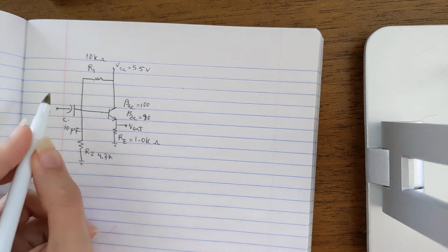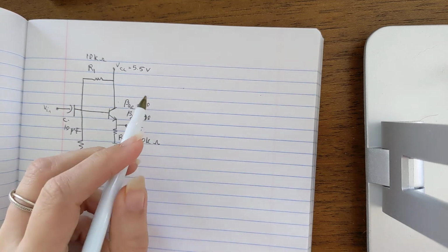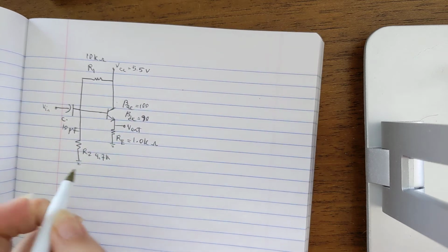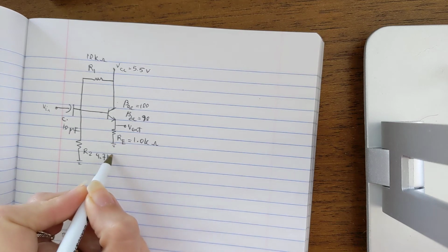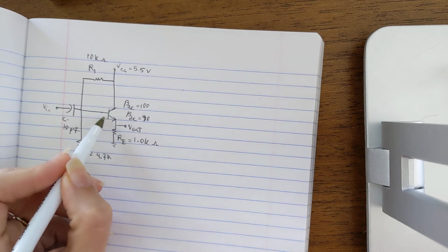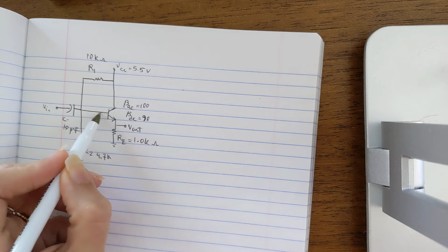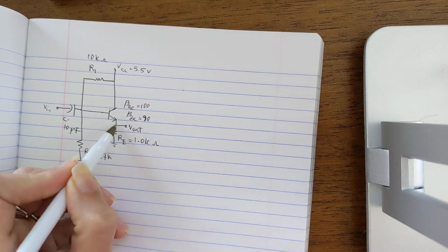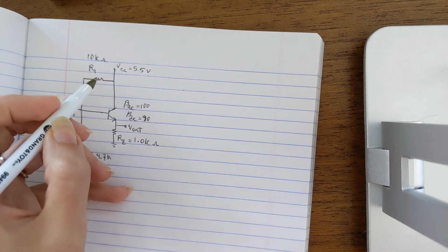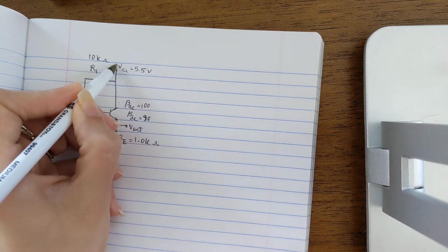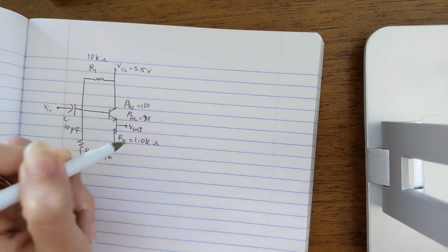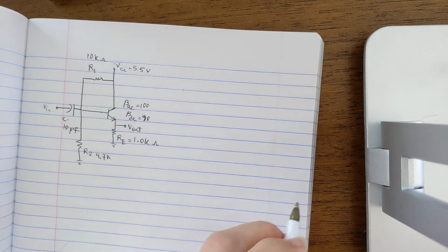So this is the first circuit that was given to you for question number 1 and question number 2. The first question asks, what is R in total here? Looking at the circuit, we see that this is a common collector amplifier because the input is at the base, the output is at the emitter, and if you consider the AC analysis here, if you ground this power supply, which we do in AC analysis, then the collector becomes grounded, and that's the definition of the common collector amplifier.